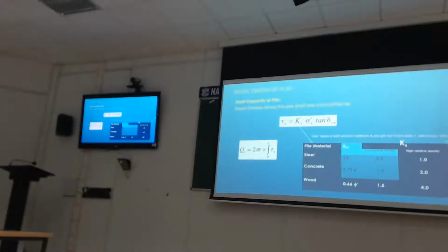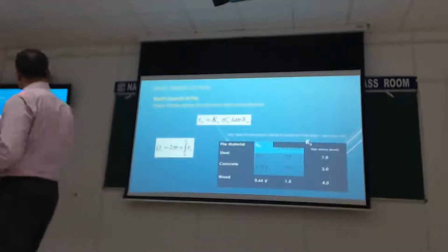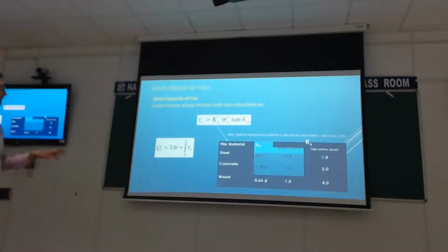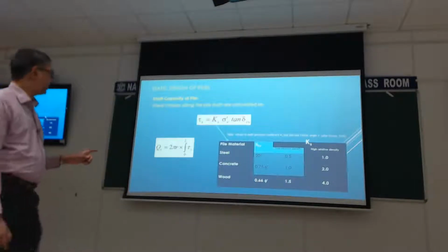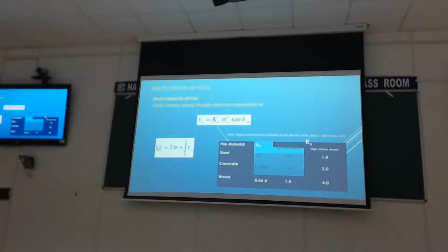And as you guys were saying earlier, the traditional way, maybe following Poulos or somebody like that, is you estimate your shear stress based on this Ks factor, sigma dash v and tan delta. We've written that already, which is good. Now, the interface friction is an important parameter in this, which goes from, for steel, using something like 20 degrees is probably reasonable because there is enough experimental evidence also to look at the interface shearing between steel and soil, and that's not far off.